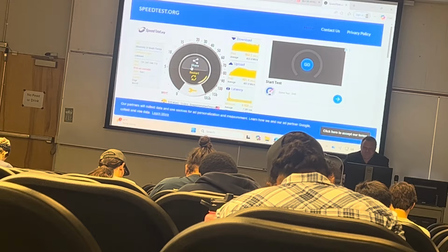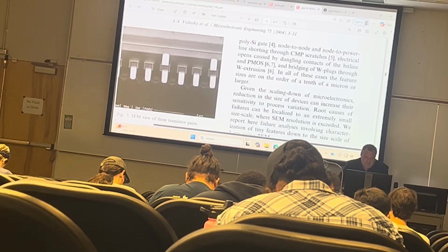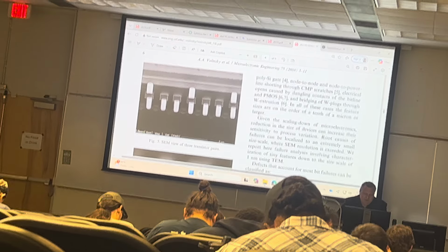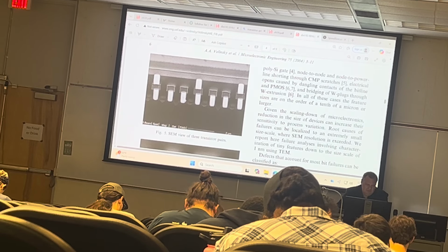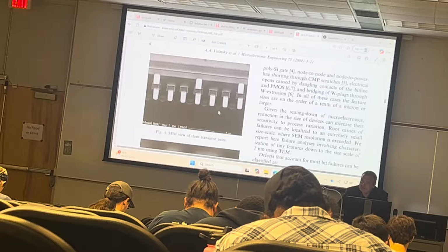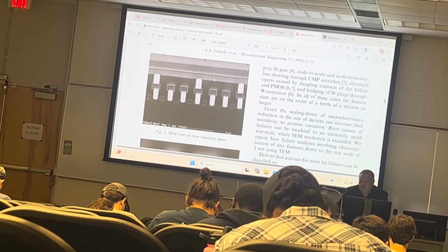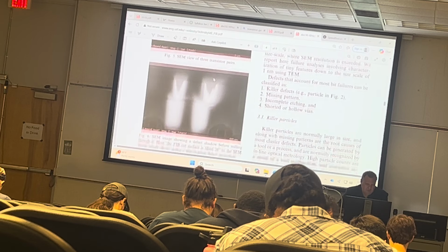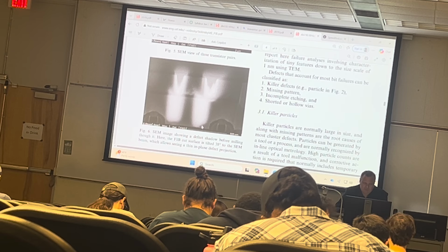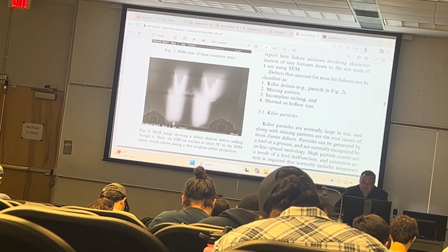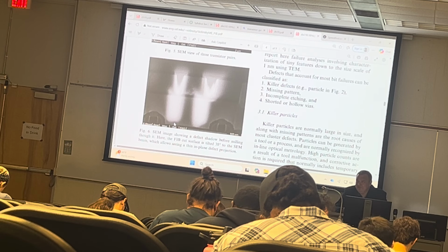So, my job was to find those defects and classify them. These are the vias that actually connect to the transistors that's made out of tungsten, and then eventually it goes to the metallization layers, which nowadays, I don't know, like more than 10 for sure. You see, this is a transistor, and this via is supposed to come down and make electrical contact. You see there's a contact missing because they didn't dig the trench deep enough.